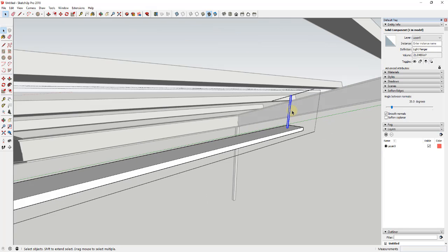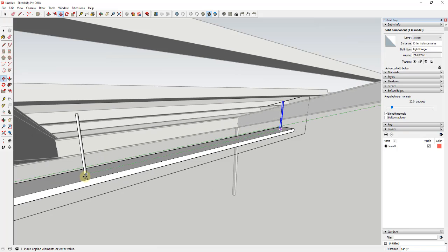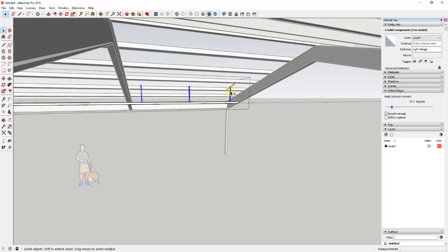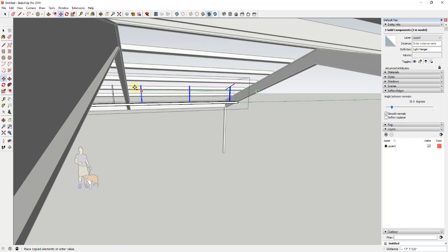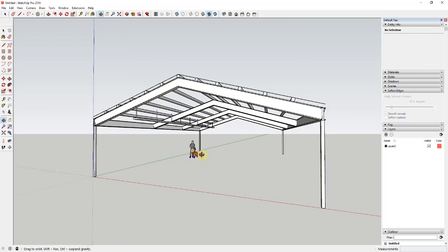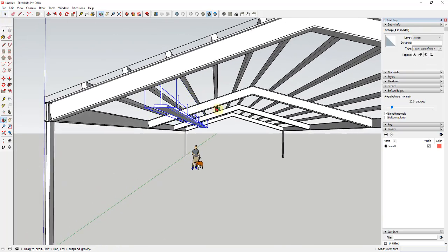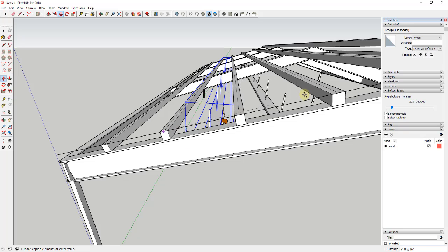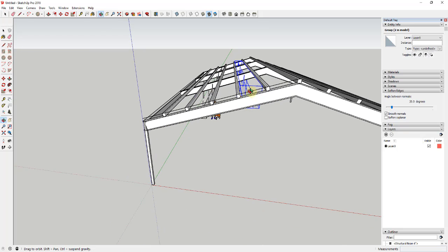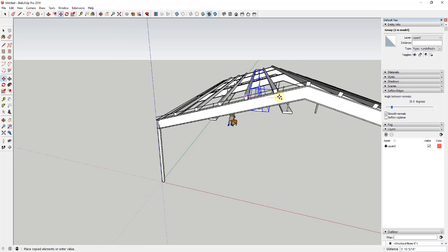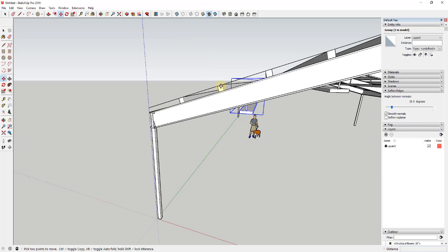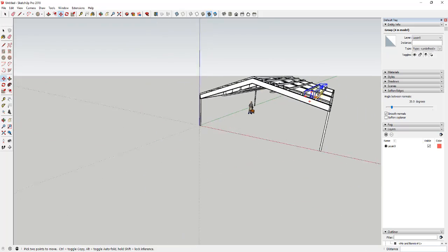And we'll just extrude it up. And that's a component, and I'm going to go ahead and create probably something like this. So I have 3 of them in here. And then I'm just going to make a copy using the move tool. So now I've got this kind of hanging light that's in here. And then I can take this, and so I'm going to make a copy so that this is sitting in this space right here, and then I'm going to use the move tool in copy mode again to make a copy here. And then finally I'll make a copy across here.